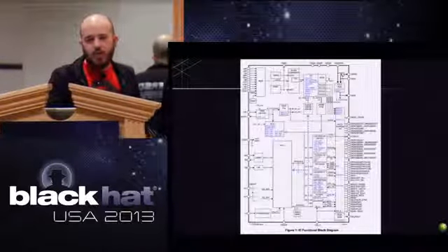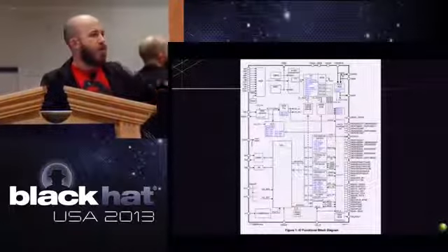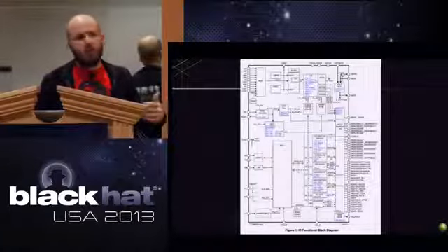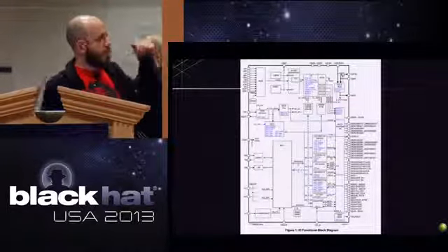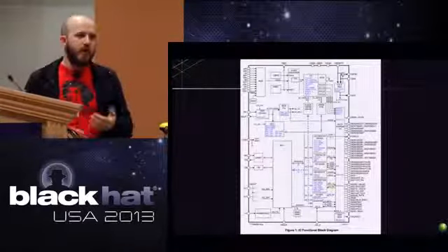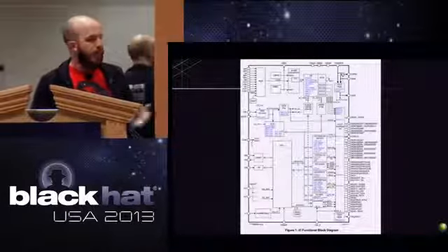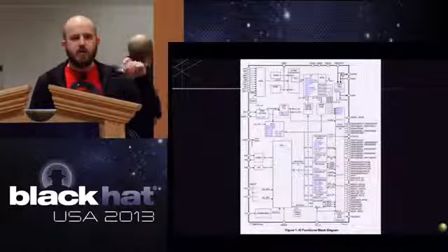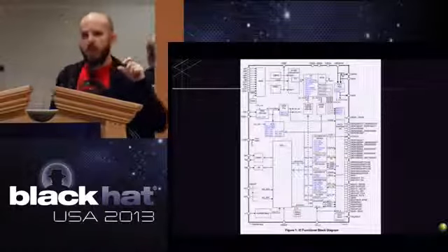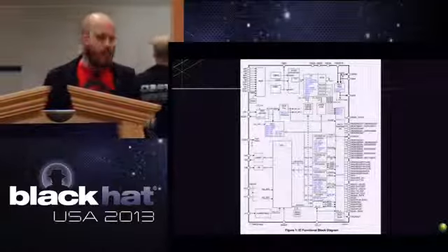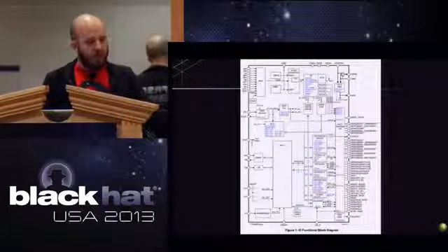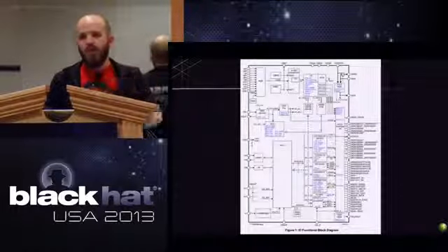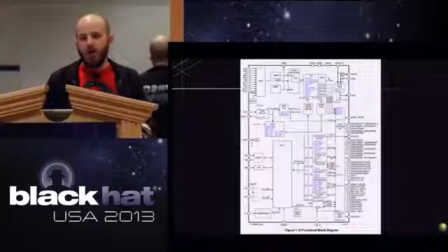So this is the overall schematic of what is inside that SoC, right? A SoC's got everything that would be needed for a given use case. In this case, we're talking smart meters. So it's got stuff to drive the LCD screen. It's got stuff to drive the pin pad that's on there. This has got lots of inputs that are designed specifically for measuring power usage in an accurate manner for smart meters, right? So all the Teridian SoCs have a very similar structure. They've got an 8051 core, they've got memory, and then they've got different peripherals that they stuffed in for the different use cases.